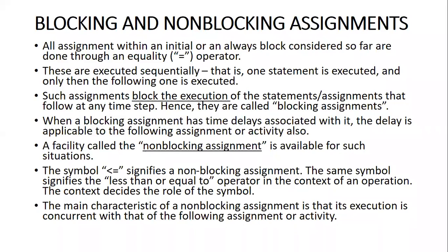Now if we have delays associated with the blocking assignment, when we add delays, the corresponding statements in the sequential execution flow will also get affected. For that reason, we'll use a facility called non-blocking assignment.